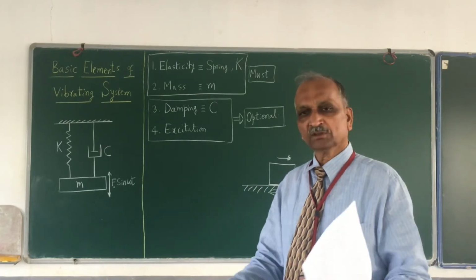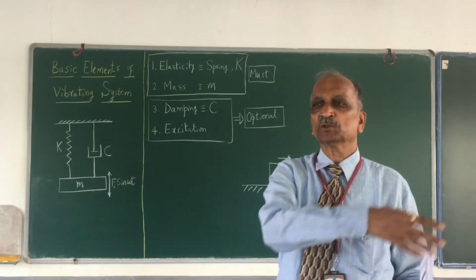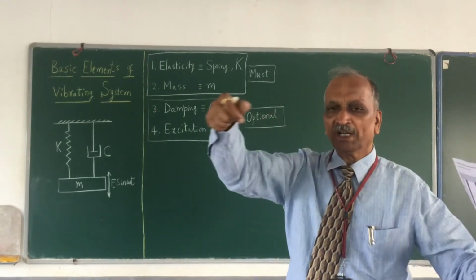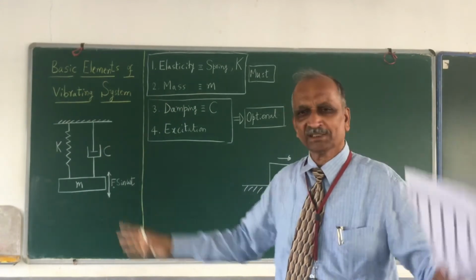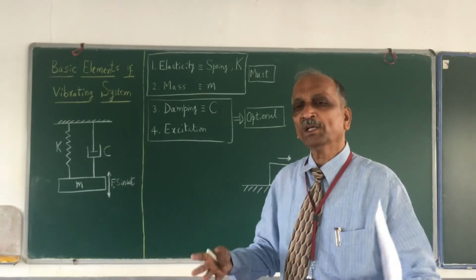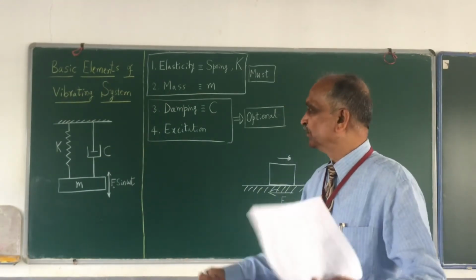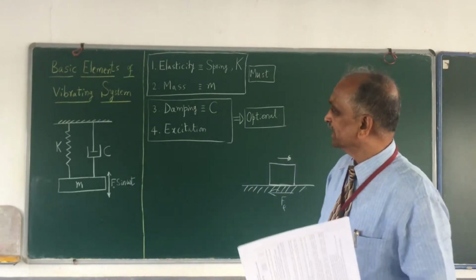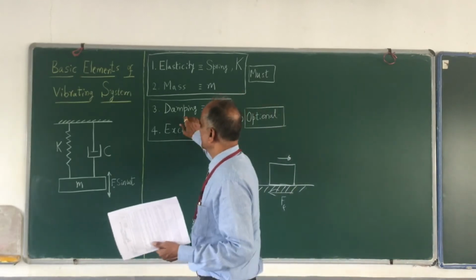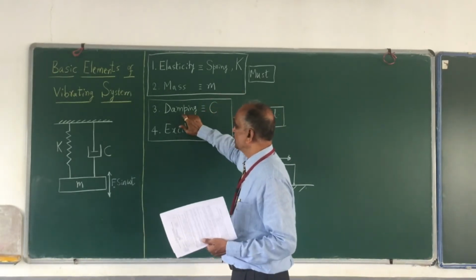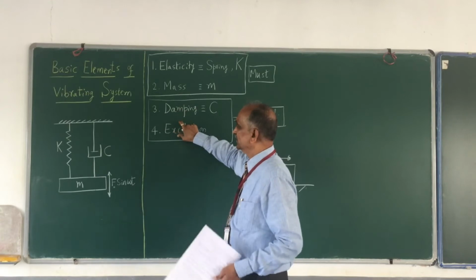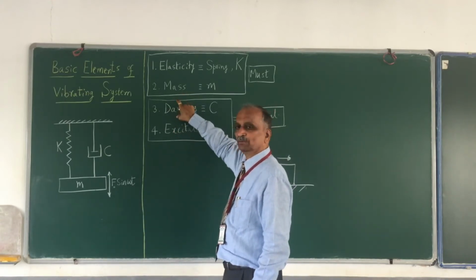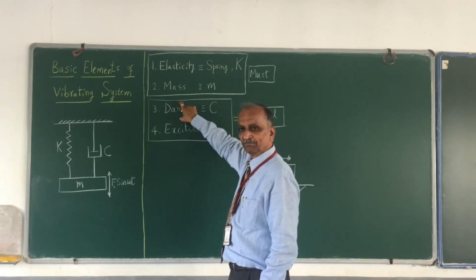That force is transferred to so many components through the piston, then connecting rod and crank, etc. So how much force? That force is nothing but the excitation. The force which is responsible for the vibration is called excitation. Any component which opposes the motion is called damping.